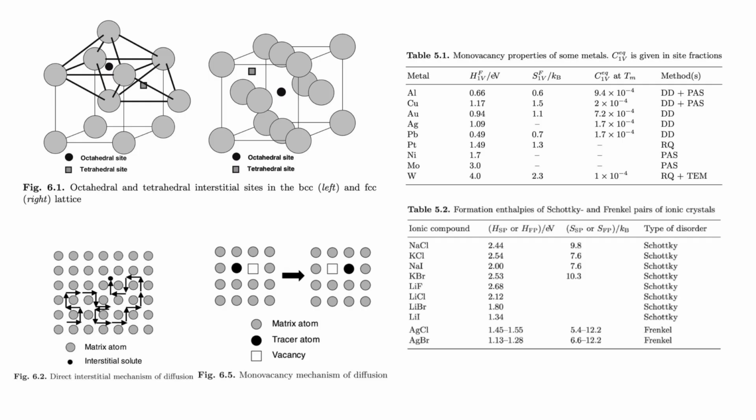If it's BCC, let's say we have 8 neighbors, it's going to cut 8 iron bonds. So actually, there's an energy penalty for you to remove an iron atom from BCC iron. But at the same time, you're gaining the entropy. The entropy now is non-zero. So we want to quantify that.